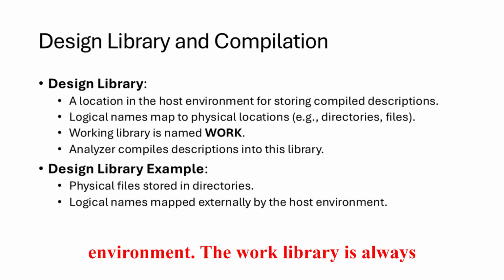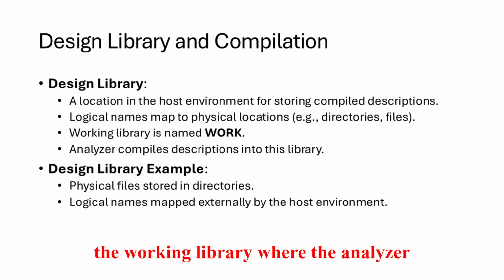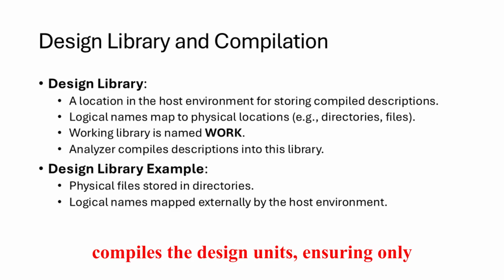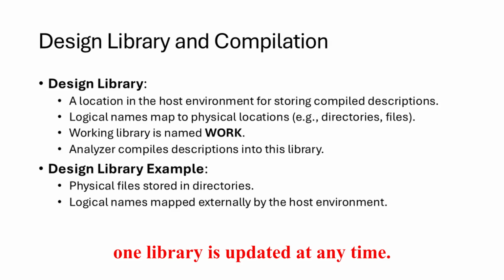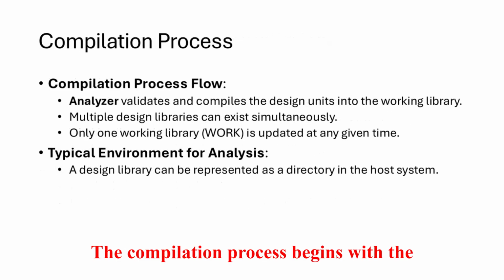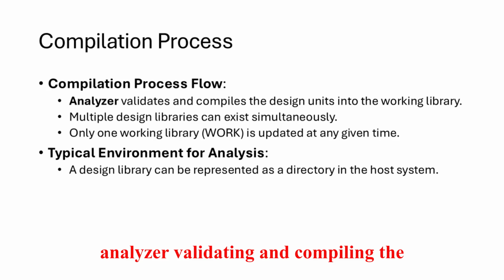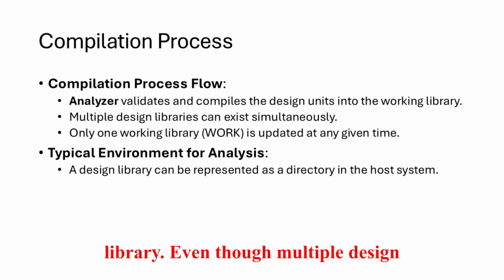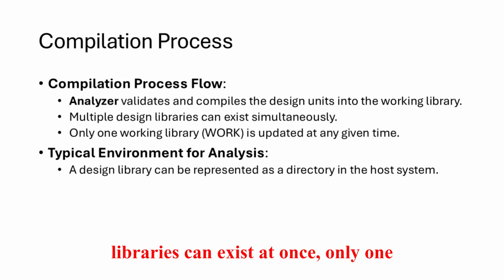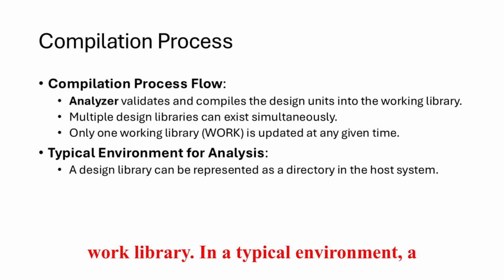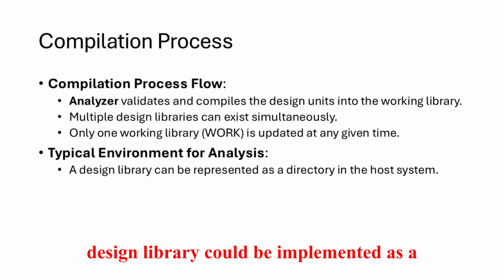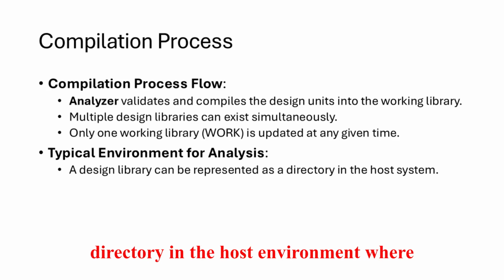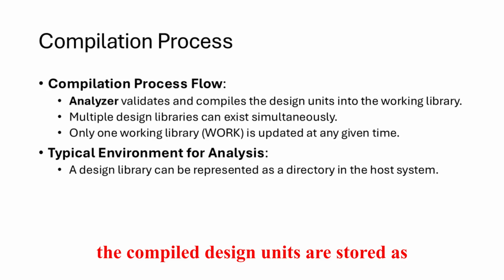The work library is always the working library, where the analyzer compiles the design units, ensuring only one library is updated at any time. The compilation process begins with the analyzer validating and compiling the design units into the designated working library. Even though multiple design libraries can exist at once, only one library is updated at any time, the work library. In a typical environment, a design library could be implemented as a directory in the host environment where the compiled design units are stored as files.